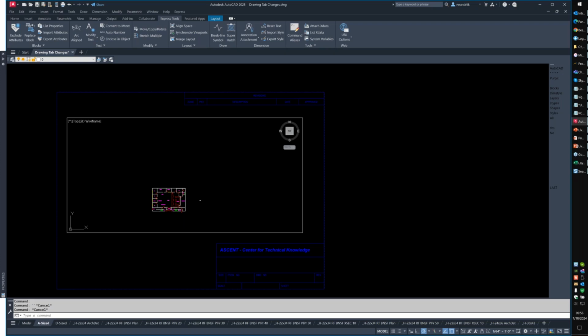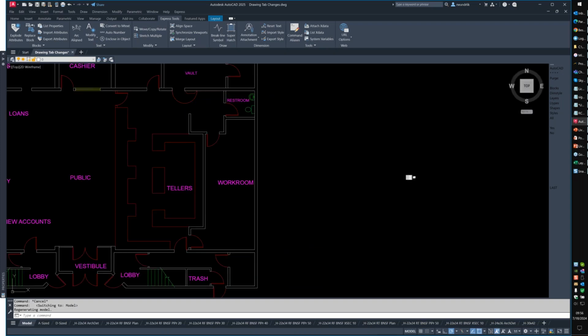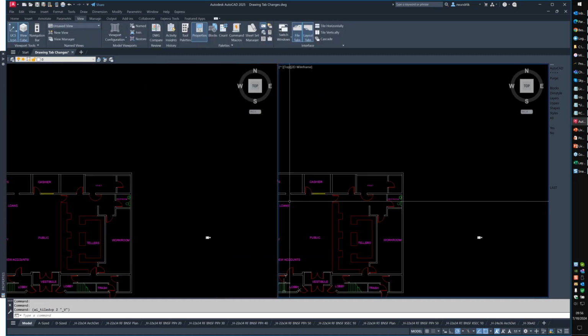Now that, Tim, is going to be dependent on a couple of things. That's actually an AutoCAD defect, where I can have a polyline that goes from a straight line to an arc segment. If I split my viewport, or let's say I split my drawing view here, I'm going to go back to model space. If I go to view and I split this into two views, that generally occurs if I'm running split views. If I go back to a single view, it usually heals itself.